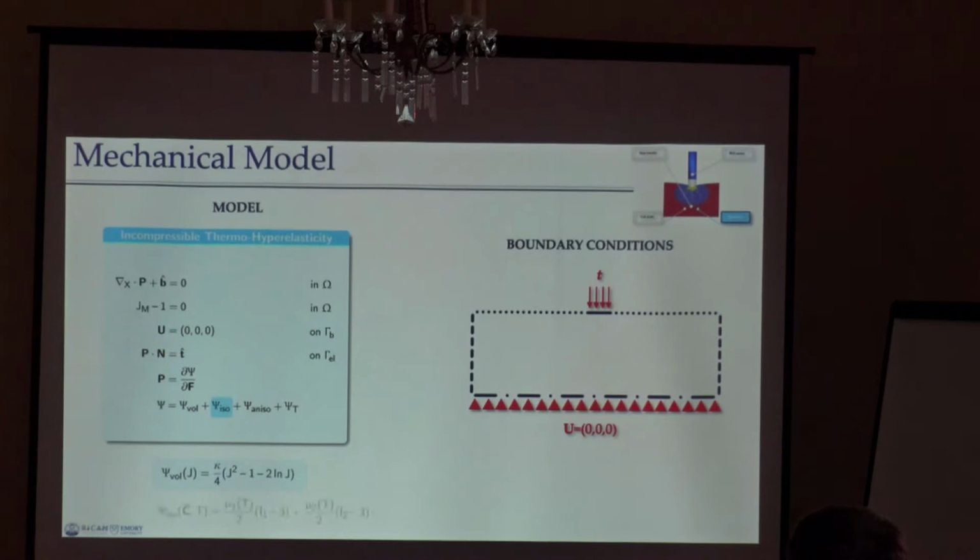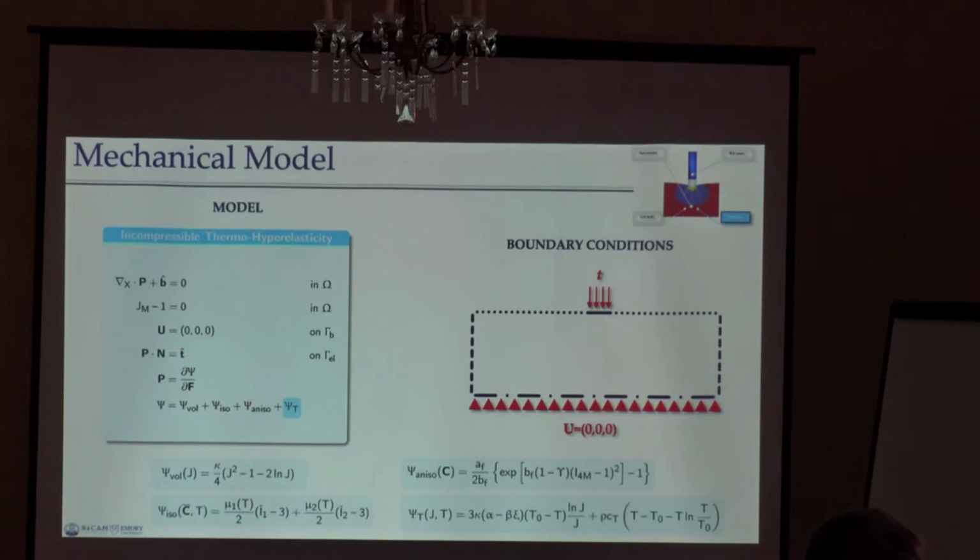In terms of strain energy density, this is the story. Basically everything is coupled with everything else, because the stiffness-like parameters in the Mooney-Rivlin model that we use in a hyperelastic framework depend on temperature. Then we have the thermomechanical strain energy density, which depends on a multi-scale parameter Xi, which is linked, as I'm going to discuss shortly, to the cell death model.